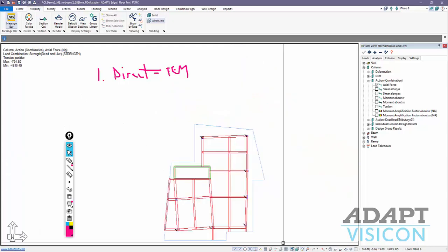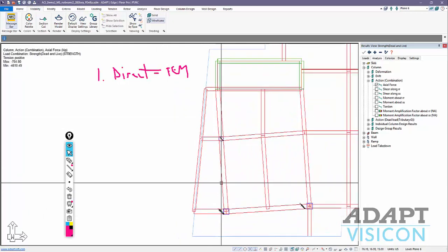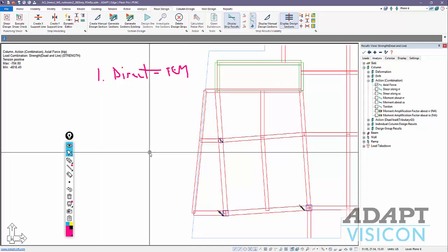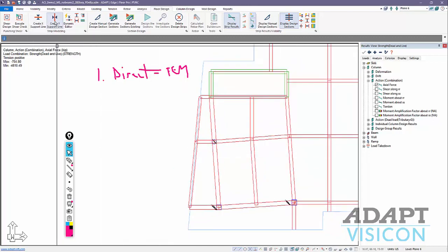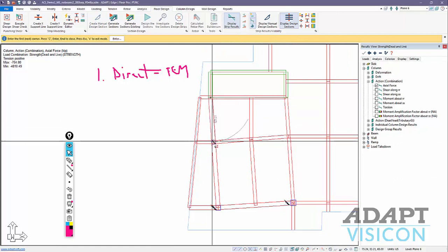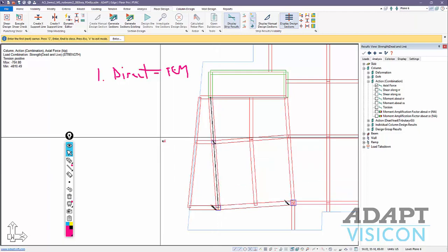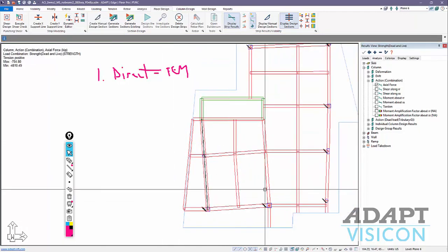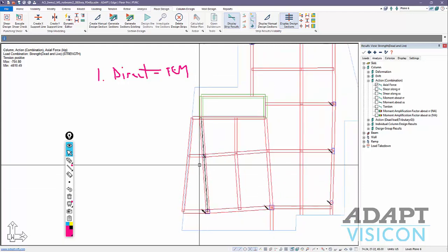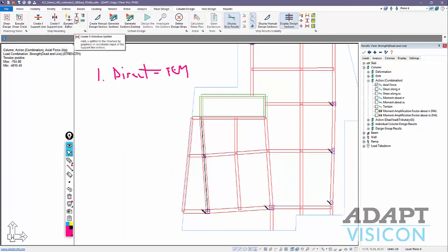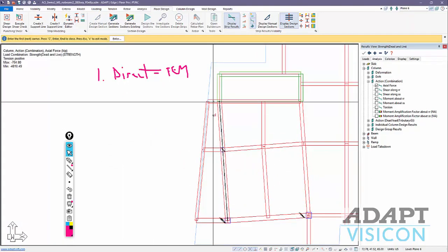So now if I take this beam and if we go back to floor design, I'm going to turn on the strips for this level. We may not have any strips. Let's go ahead and create a design strip. So I'll use the X direction, and we're going to go from end to end like so. And then I'm kind of isolating the beam from the rest of the slab here. Typically we would have support lines on all beams if we were to design the entire system, but here we're just isolating one.